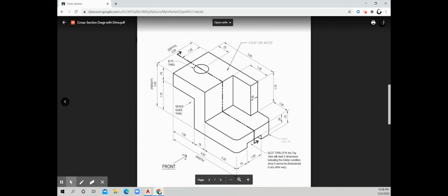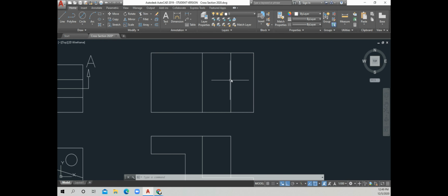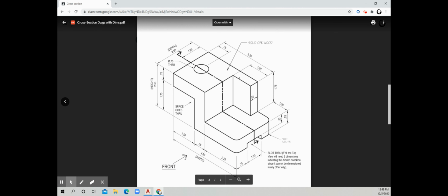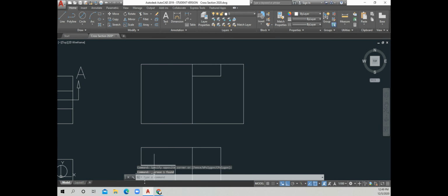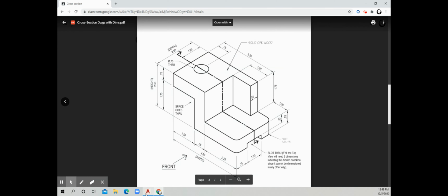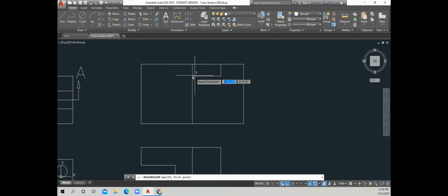So we need to go a 1/2 inch down and over. Now, so this whole line doesn't remain here, you can just go ahead and get the line tool. Let's just follow this line, 0.5, and then bring it right over like this. And now we can go ahead and just get rid of that. And that'll give us the little shelfy looking thing there. Not sure? Let's take a look here. This should be 1.25. Let's do a check. Here's the measuring tool. Distance of 1.25, same as 1.25.